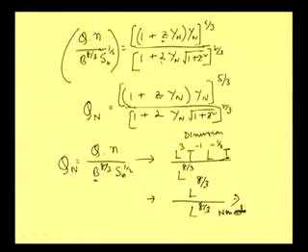Okay. So that way we write this Qn as non-dimensional discharge. Well, now using this, if we see whether we can avoid those earlier conditions, that is the requirement of trial and error method for solving.